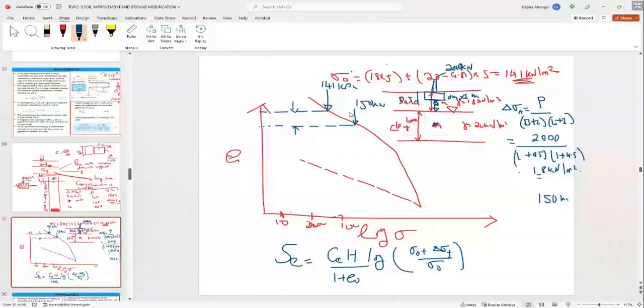Now, there is one thing that we need to determine from this curve. Soil has a memory. You're able to determine the past stress to which the soil was subjected. It's called the pre-consolidation pressure. From the point of maximum curvature, you draw a straight line, and then draw a tangent to that. Then divide this into 2. And then from the other slope, bring a line.